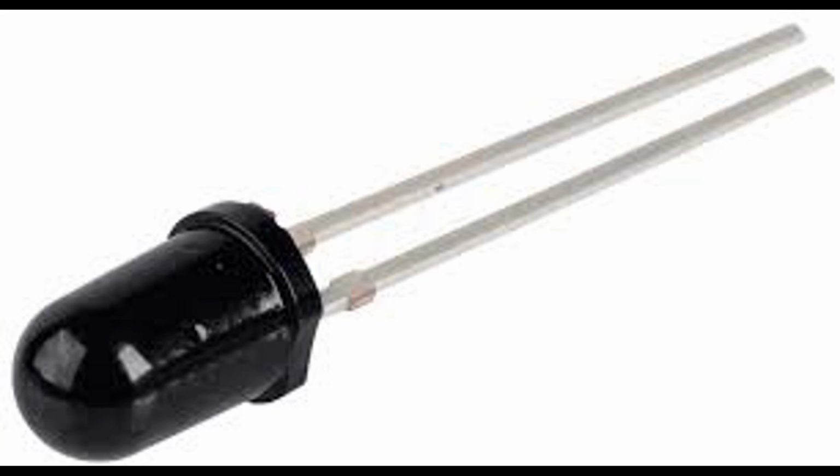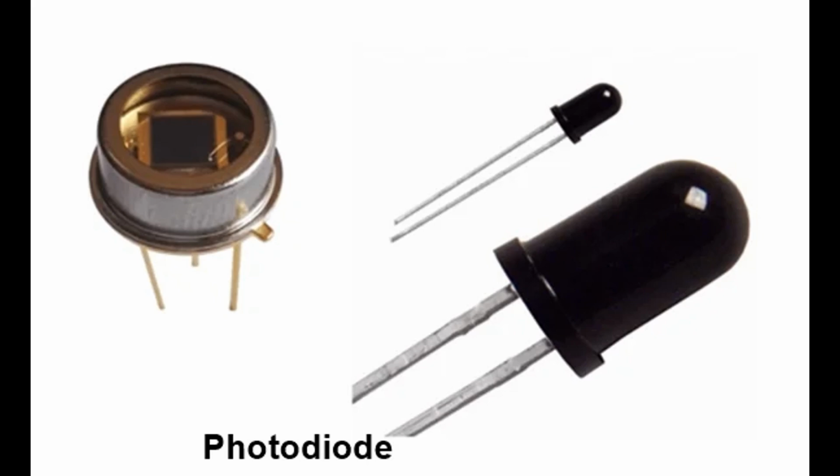4. Response time. Capacitance of the P-N junction and the size of the photodiode affect how fast it can respond to changes in light intensity. Smaller photodiodes, or those operated with reverse bias, typically have a faster response time. Speed. Faster response times are critical in applications like fiber optic communication, where high-speed detection is necessary.